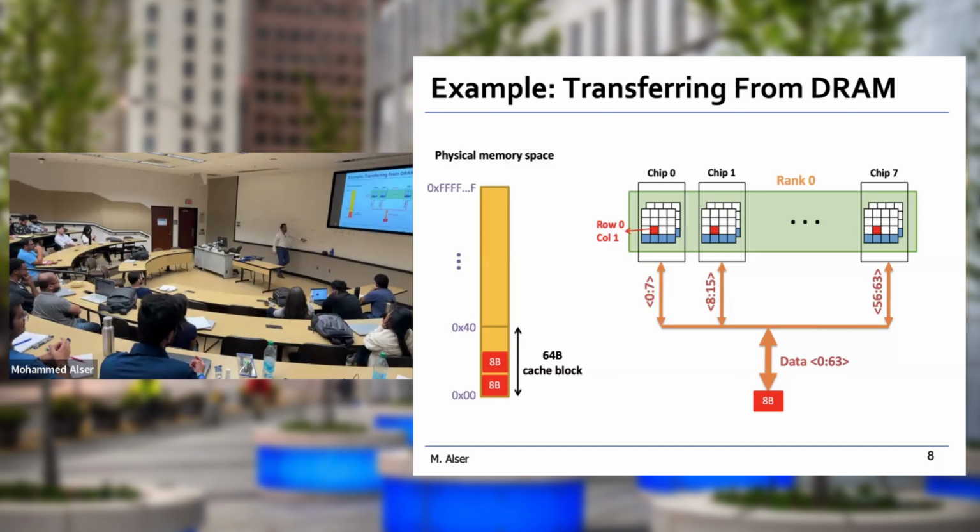You need to divide, like one row will get 8 bits out of it. So you divide those 8 bits into a chip, the second 8 bits into another chip, the third 8 bits into another chip, such that when you access the entire row, you access it in the exact same time from all chips altogether. That means I need every 64 bits of the matrix to be divided over several chips. In this way, I can access those entire 64 bits at the same time. So every time I send a request, I get 64, 64, 64. That's for the entire row.